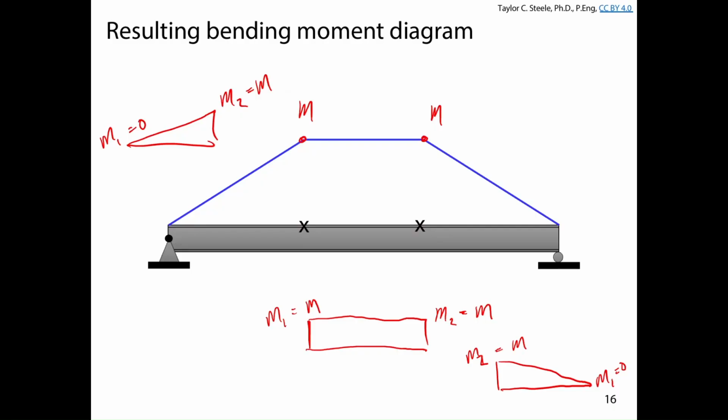Why is the middle one more critical, do you think, then? So we've got equal moments at both ends of the beam. Why does that make that segment more critical? The unbraced segment length is the same for all three. The maximum moment that we would check, so Mf, is still the same for all three segments. Why is the middle segment more critical? Well, L is the same for all three. We'll assume the length of the girder over 3 is the unbraced segment length. But we also have omega 2 values to consider.